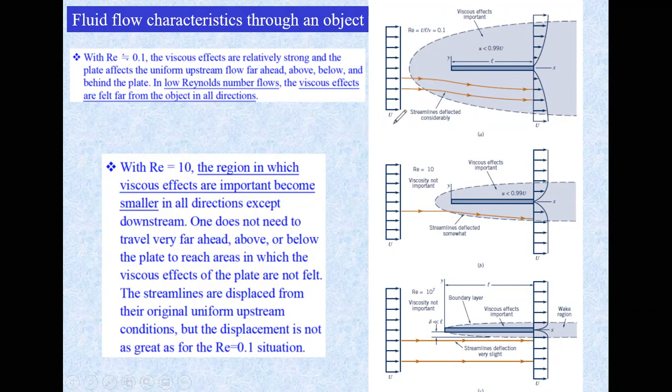geometry. So if you have this shape compared to, for example, this shape, then you have two components of drag. First is the shear stress at the wall. The second one is the pressure force, which also causes drag. Remember, the drag and the lift are a combination of the pressure force and the shear stress force.